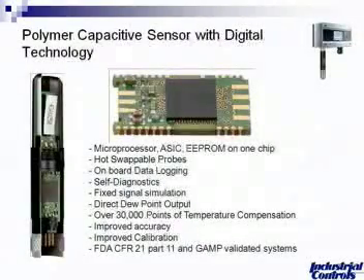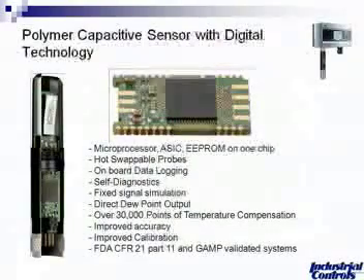And what that will allow you to do is basically you now have a hot swappable probe. And that comes in big in the service areas. And we'll talk a little bit about that further on, but you no longer need to pull the whole transmitter off the wall to do a calibration. You can just swap the probe because the probe now stores all the calibration data for humidity and temperature.